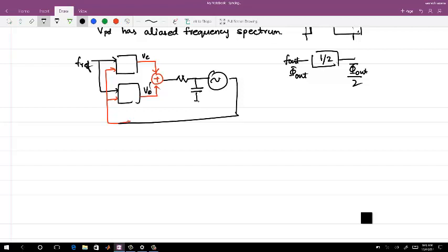Okay, so aliasing will surely be there. Right now I am considering only one single frequency, and I am sampling at another frequency, so that aliasing will be very clear because this will turn out to be a DC. But when you have noise on the reference, how does it alias? Then again, it depends on the filter bandwidth. So we will come back to aliasing with this kind of PLL when we look at the whole PLL architecture and see how this is a problem. The other thing is the reference noise is normally very low in the system, but if you alias a lot, it will be trouble.